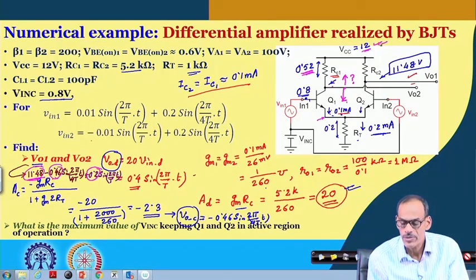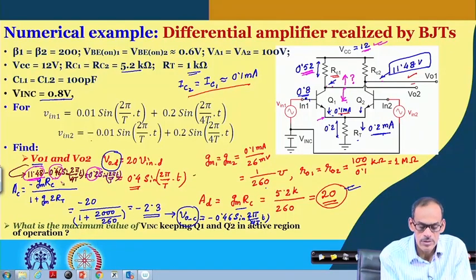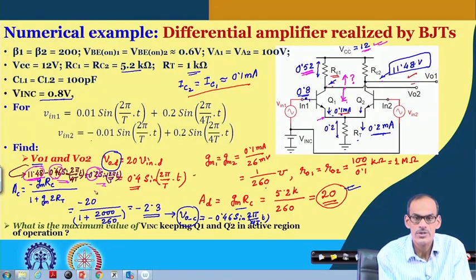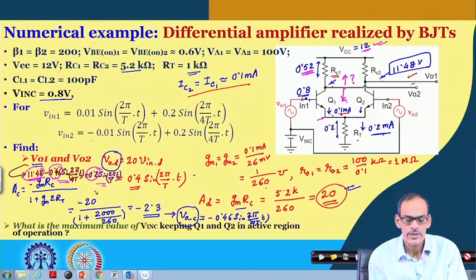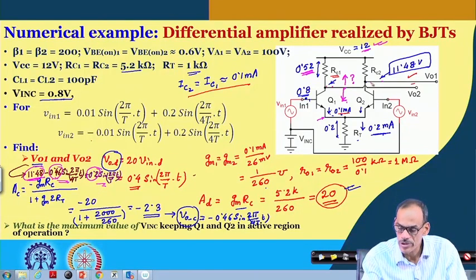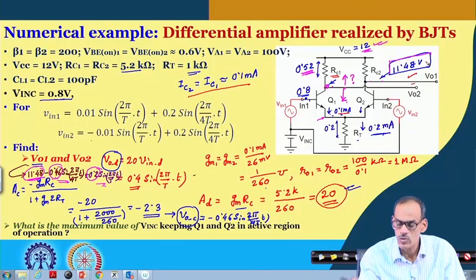So, what it means is that at this point and this point, the signal combination of this common mode and differential are getting distorted, because the voltage here cannot exceed this 12 volt, indicating that the DC operating point is too high.